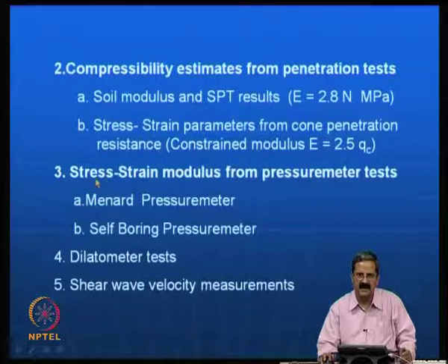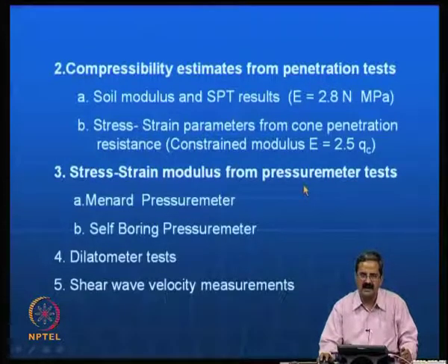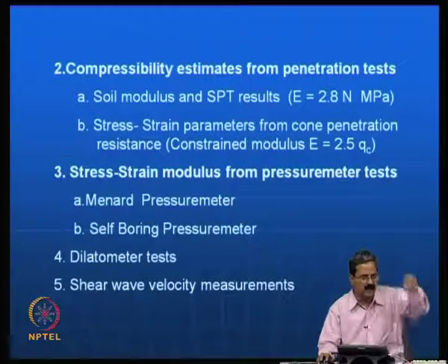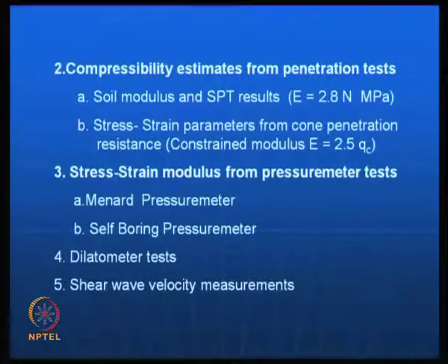There is another equipment that we use in a very nice manner, which is called the pressure meter test, in which you have a small tube which has a diaphragm, and once you insert it, it expands and then you try to find out both the deformation and the pressure exerted to create that deformation.